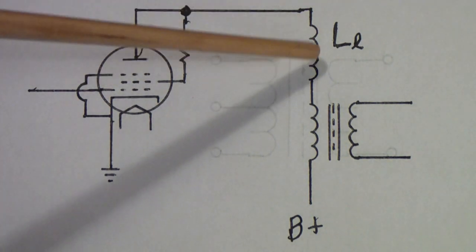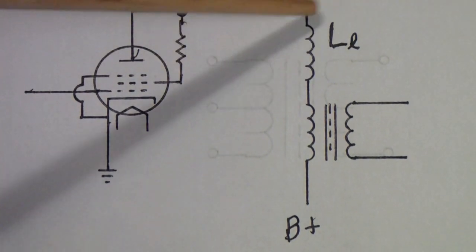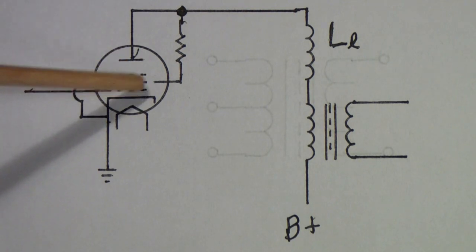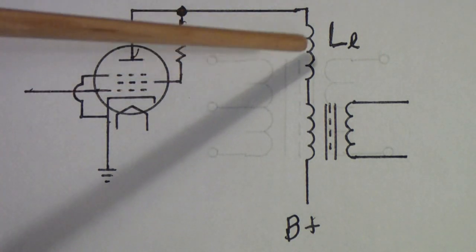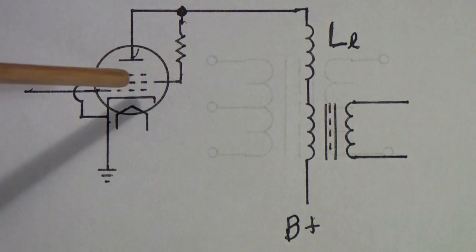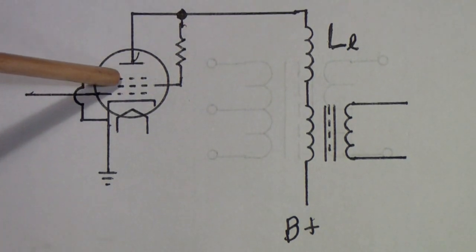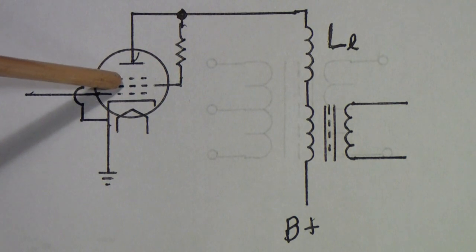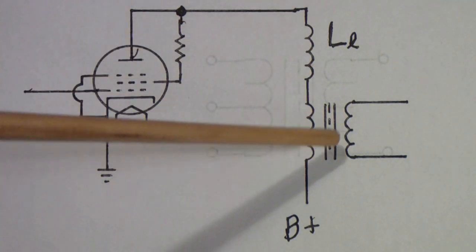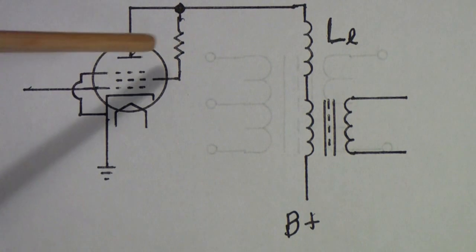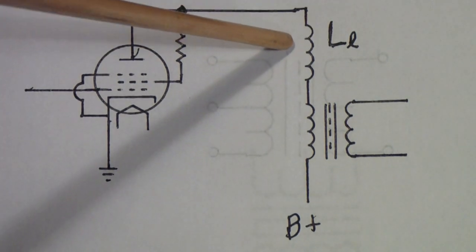And the problem with that is it induces an additional voltage into a tube circuit that is not present generally in transistors. Now that doesn't mean that transistor AB amplifiers don't have crossover distortion. They do. But tube amplifiers using output transformers have additional crossover distortion due to leakage inductance.